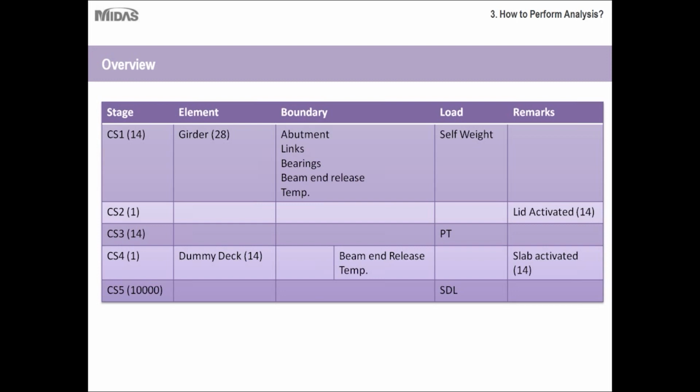And it is at this stage we'll remove the temporary supports in the beam and releases that were there to simulate the splice connection and the shoring members. And then the final stage is that where we'll be applying the superimposed dead loads on the structure and see the permanent condition of the bridge. So for this stage, we'll be monitoring the structure for over 10,000 days.